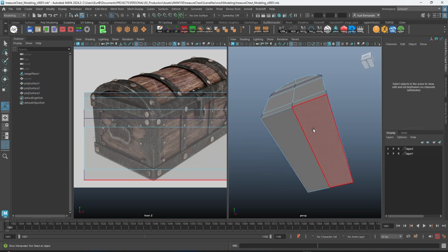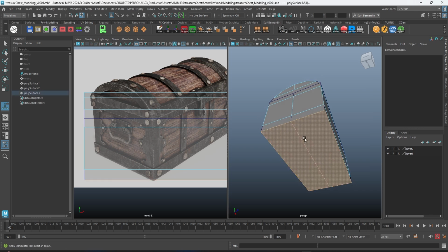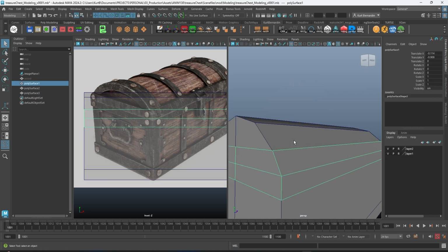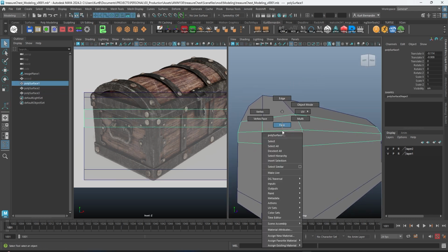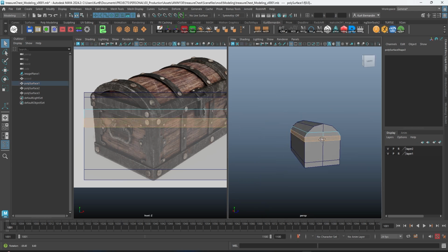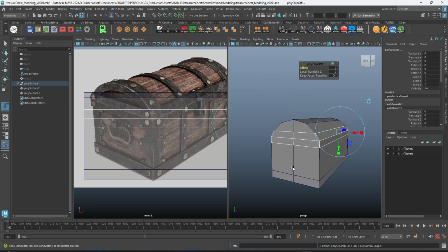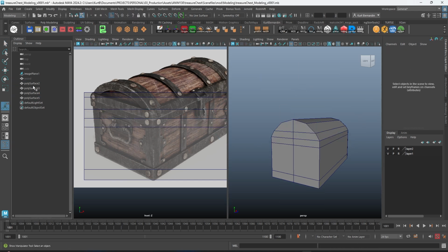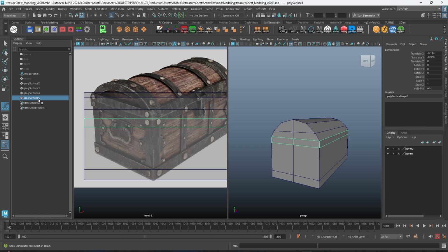And if I rotate the camera, notice I have these faces down here. For now, I'm just going to delete those and then grab this piece of metal right here. Since this is where the 2 pieces connect to actually open, close, I'm going to go ahead and separate these as well. So I'm grabbing this whole face loop, and do an extract faces. And now notice how I have an additional piece right here.